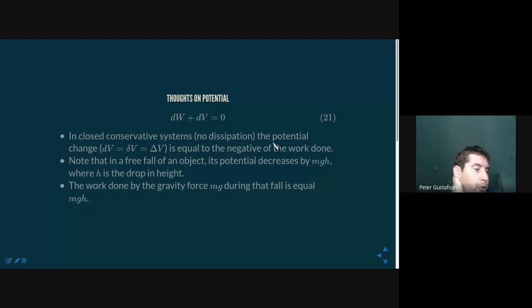Ethan says we were a slide or two back. Ron says, so would P be like a spring force? Yeah, absolutely. In this example, we're storing energy in the structure as it's deforming. And so that structure is acting like a spring. It is a recoverable energy that you can use to actually do work. And that's what a bow and arrow is. You're deforming a structure to store energy and then recovering it, and turning it into a different form of energy.